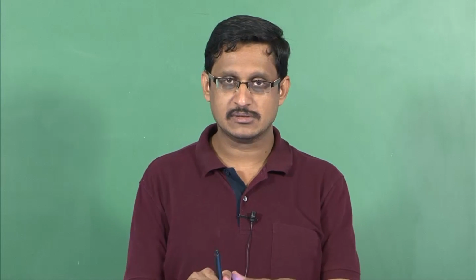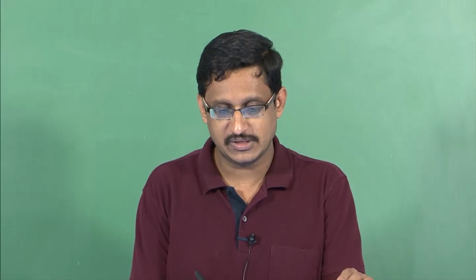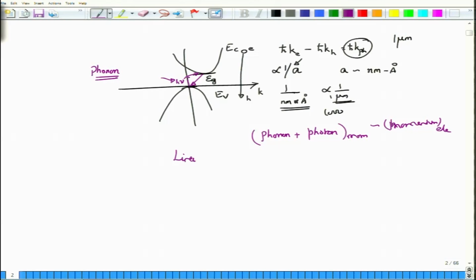So this is some absorption characteristic, and what is important here is that the line width is essentially proportional to the temperature, because increasing temperature increases the spread delta EC and delta EV, which increases the range over which emission can happen.